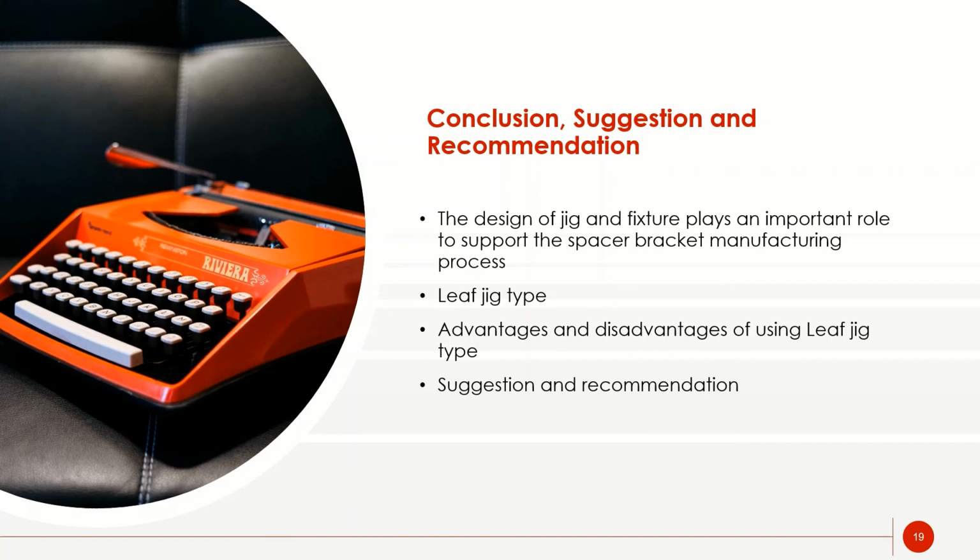Since the design of jigs and fixtures is dependent on numerous factors which are analyzed to achieve an optimum output, they should be made of rigid, light materials to facilitate easy handling. If you are able to make the jig and fixture, we suggest using mild steel with 16mm thickness, which was chosen for the design of a sample jig and fixture for adequate strength and rigidity.